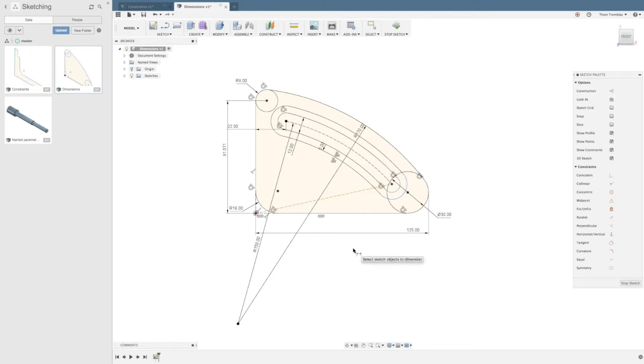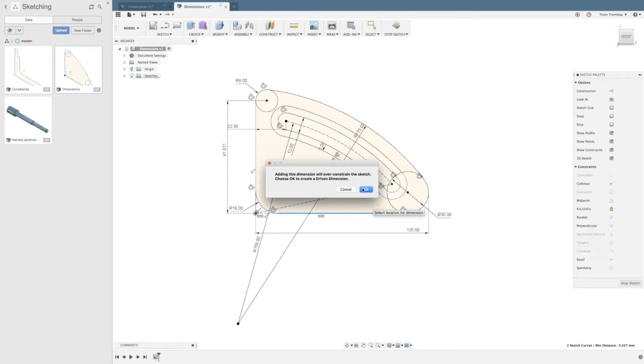But I can use the dimension tool, select the first line, and get, of course, vertical, horizontal, aligned. But when I select the second line that isn't absolutely perfectly parallel, it automatically changes this dimension type to an angle. So, I must have over-refined my sketch.